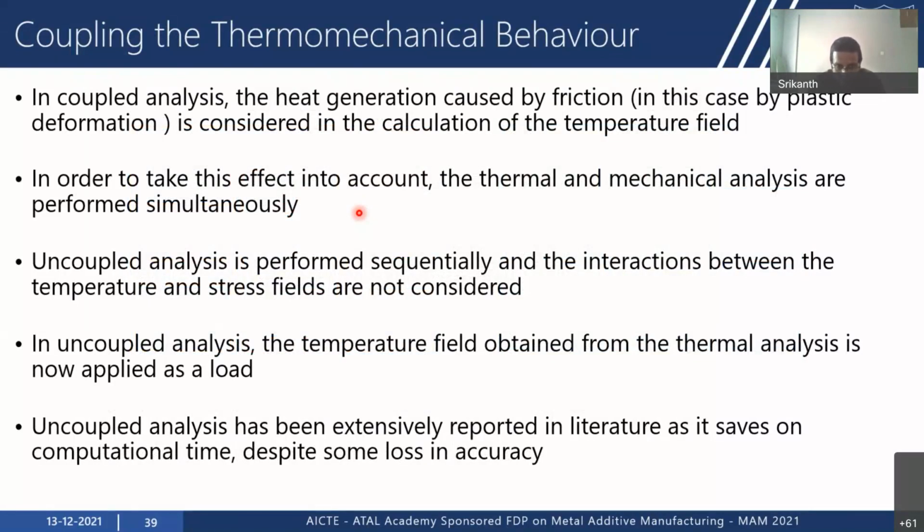So it increases the number of equations that need to be solved in each time step. Now, in the case of uncoupled analysis, as the name suggests, it's performed sequentially. That is, upstream affects downstream, but downstream does not affect upstream. Thermal analysis affects the mechanical analysis, but mechanical does not affect the thermal analysis. So the interaction between the stress and temperature fields is not considered. What we do in the uncoupled analysis is that the temperature field obtained from thermal analysis is applied as a load to structural analysis.